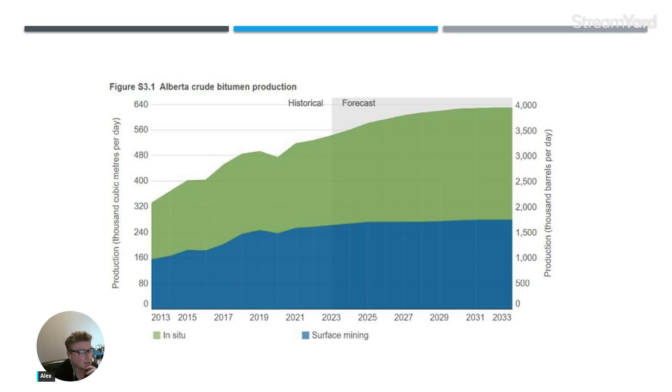So I guess what I'm trying to say is that one of the big constraints for the industry through that process that you guys are going to be learning about is that ability to handle stuff at the surface, right? Because nothing here is infinite. And somebody, John, here said you're limited by operating capacities, which is correct. But your operating capacity is also a function of flow rate, a function of steam injection capabilities. So you can't generate infinite steam.